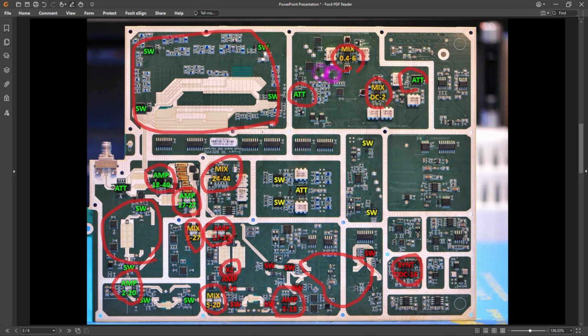There are transformers and many switches in order to switch all the different IF signals generated by all these different mixers to ultimately reach the ADC, which is sitting on the other board. And there is a switch over here and a switch over here with many paths going in there, programmable attenuator, and on the other side of this board right over here are the connectors that bring those IF signals into the other board. And that's how these things essentially interact.